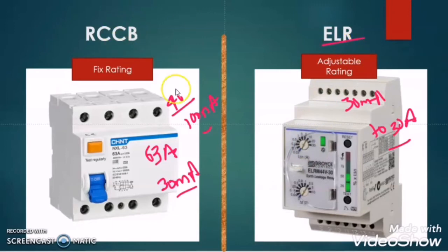Moreover, suppose this RCCB has a tripping time of 4 milliseconds. Means when it detects the fault, it will trip within 4 milliseconds. We cannot change it. But in the case of the ELR, we can change the tripping time also.